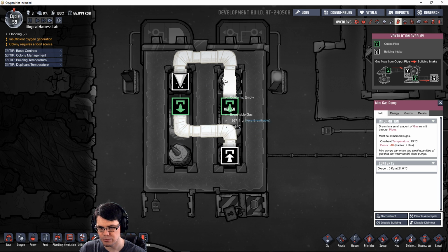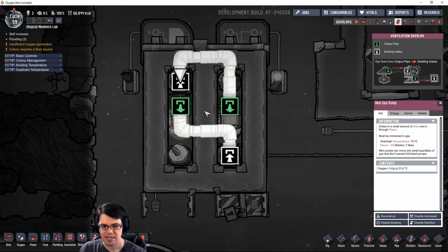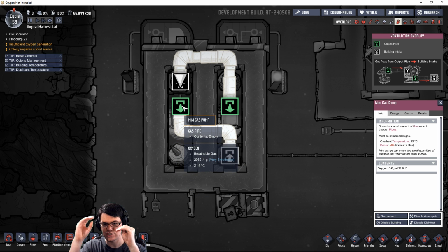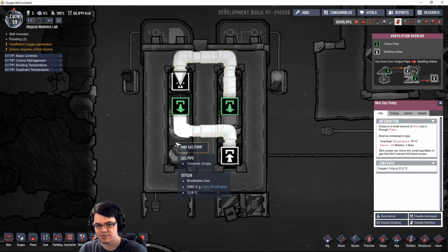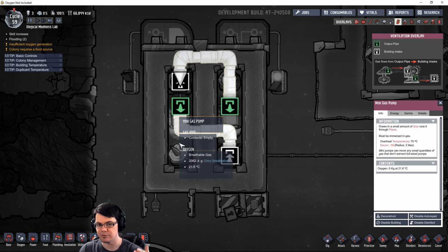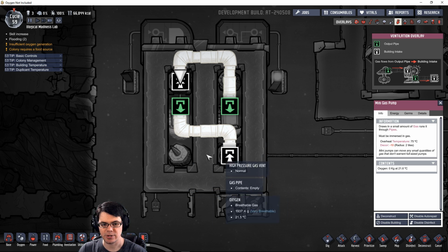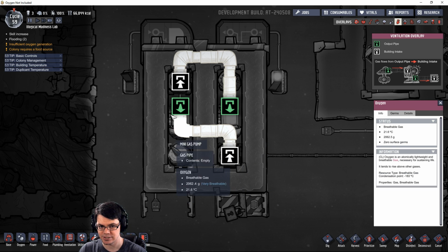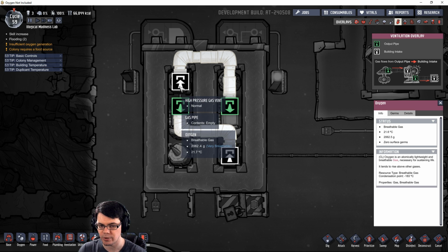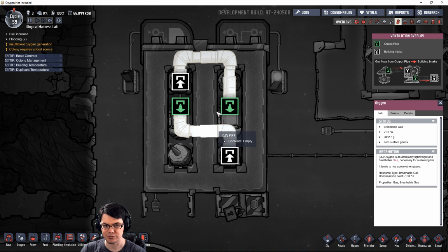However, when I did 3 gas pipes, and then I threw the sensor right next to that, there was a chance that the overpressure coming out of these vents would cause this signal to spike up before the chamber balanced. So having the sensor down here on the other side of the pump, a little bit farther away, allows that chamber to balance out before that switch clicks over. That way you don't end up in a situation where both of these are green, allowing both pieces of equipment, whatever it is you're trying to synchronize, to go at the same time, because that wouldn't really be good.